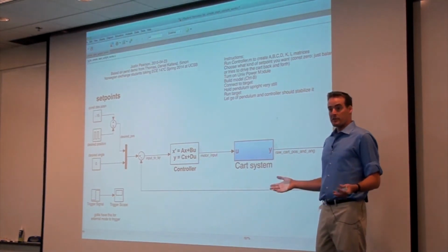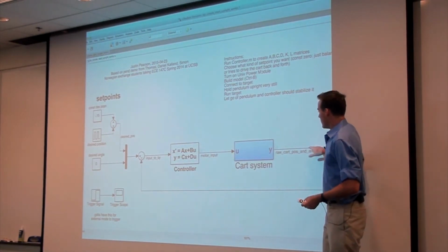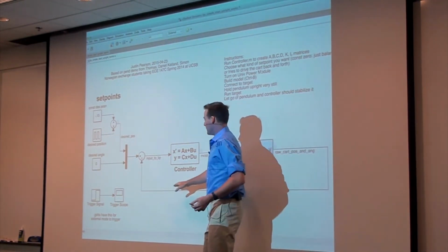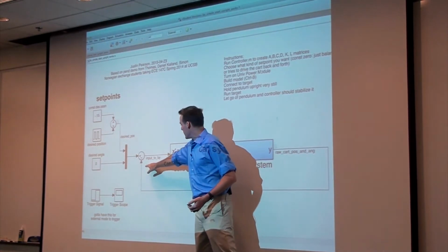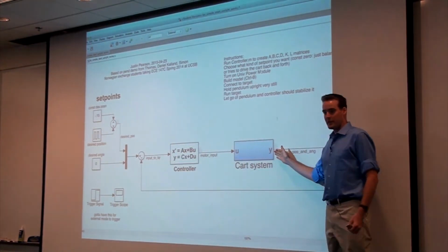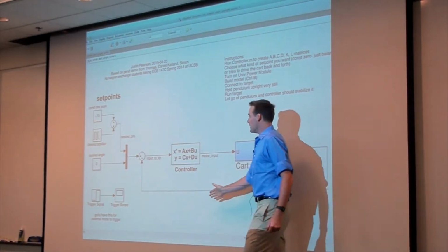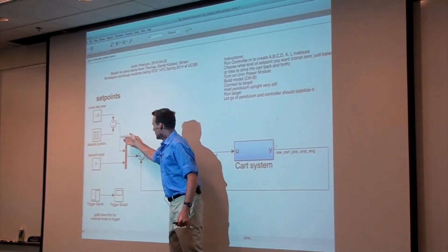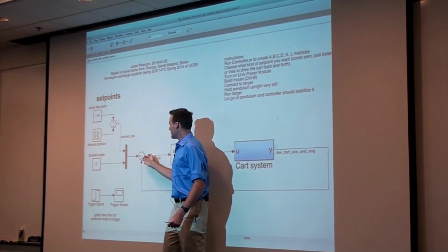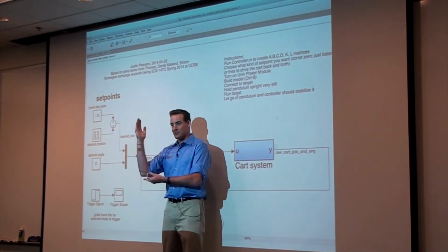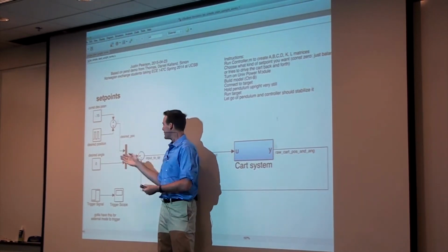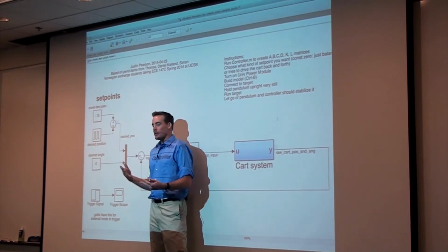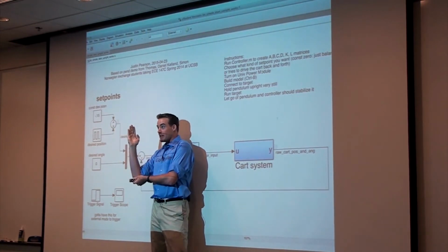And we teach our kids in ECE 147C that this is a very common method of control design. It's called negative feedback control. So you're feeding back the actual cart position and angle, and comparing it, subtracting it from the desired position and the desired angle. Here the desired angle of the pendulum is just 0 because you want it to stay upright, you want it to stay inverted. And the desired position of the cart, well, it could just be 0. That would mean it would just stand here balancing.